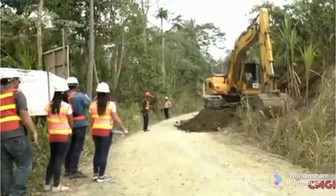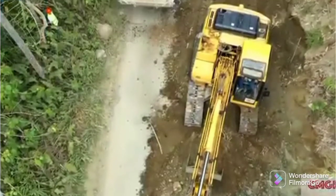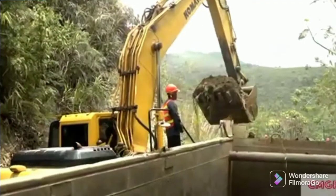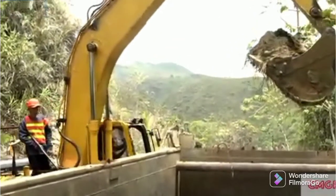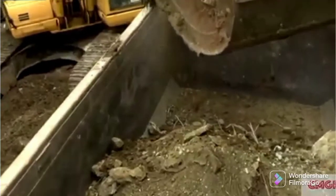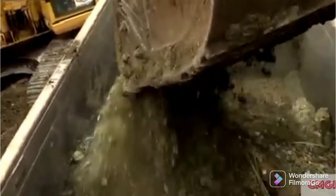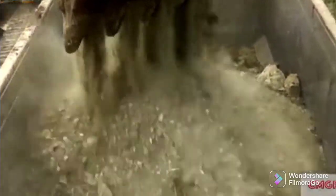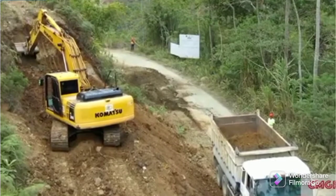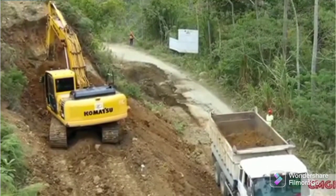In road construction, it all starts at clearing and grubbing, where the unwanted organic piles are taken away so that the soil on the land will be prepared for the construction of the roads. It is very important to remove the biodegradable or organic material from the site because it will affect the quality of the road that will be constructed. Here they use the proper equipment or machines or just manpower.